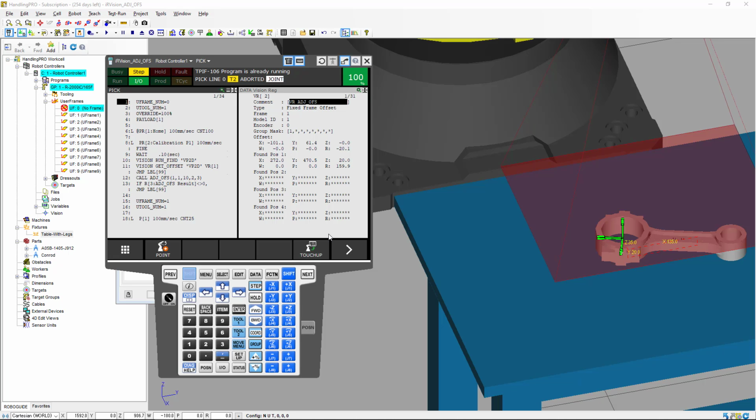So this way you know how to use position register number 10. Originally you select the value 0. You rotate the part 180 degrees. You calculate the offset from the position that you are at to where you want to go. From that offset, you divide it by 2, and that is the value you want to adjust on position register number 10.